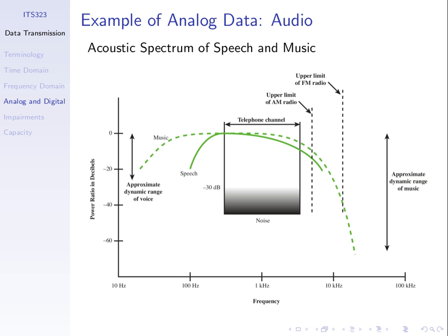So just an example of data, the green lines, and two example transmission systems which you know about, FM and AM radio, which have different bandwidths. And therefore they can only carry the signals up to that bandwidth. FM up to 20 kilohertz, AM up to around 8 or 9 kilohertz. AM cannot carry music in these high frequencies. FM cannot carry music in these very high frequencies of music. That is, FM can carry most of the music, AM not so much, and therefore the lower quality.